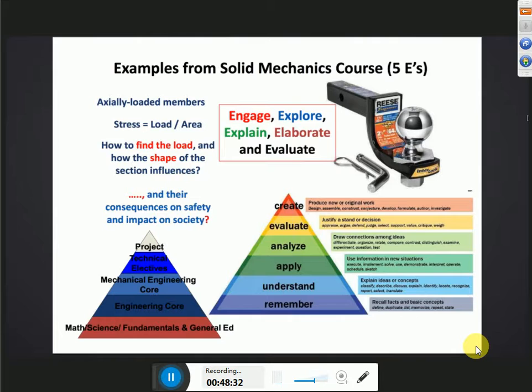This can break. That brings us to the modes of failure. It can break here. This can get pulled off because it's welded. There are different ways it can fail. We've got a pin. But if you look at only this section and draw a free body, basically that's in tension. So we can ask the students to explore this application. They may not have seen it, but they should explore on the internet to find the cross section of this. And then of course that becomes a real life example from a simple tension example.